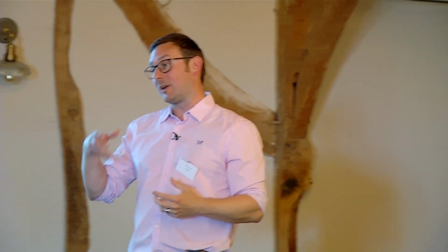So I think, I was talking to Barry about this earlier on, I think where I would utilise the guidance is advisory aspects relating to exactly that. So you can say, when you do your pre-acquisition surveys, that if the building were built now, the current layout and design would not meet the requirements of the building regulations, Part B1, Schedule 1. You can say that when you do a pre-acquisition survey. And then you can go on to say, ADB Volume 1 says this. Now, there's no legal requirement for you to do this unless you start doing other building works as defined within Regulation 3. But if you do, you should be aware.